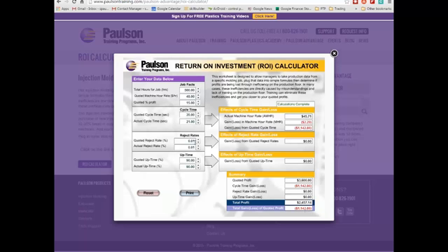Now my reject rate, right here we're at 1%, 1 out of 100. Well, things didn't work out so good. So the reject rate goes up, I don't know, a fair amount. That doesn't seem to cost us much on the surface, just $20 in this case. But these are pretty low reject rates. My assumptions are pretty low here. That could easily become more, and this doesn't include the cost, you'll notice, of finding them, grinding them, and reintroducing that material back into the process if you can, or eating the cost if you can't.